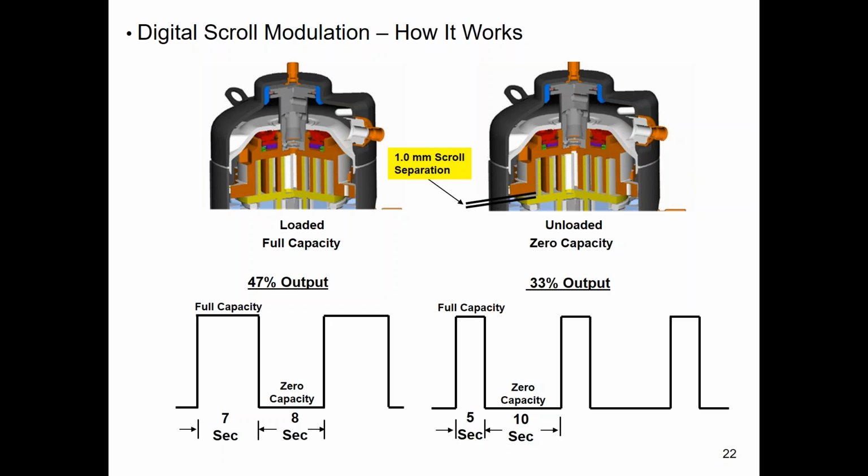There are some coils that they're putting so much in there that you end up having to have higher point suction stub outs, which require the drain line. It's not many. It's maybe 5% of the coils out there, but I run into them probably 3-4 times a year.